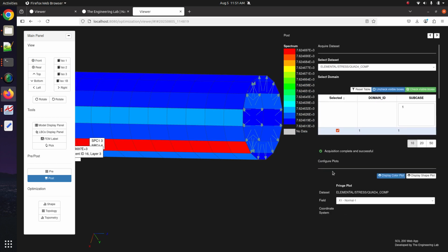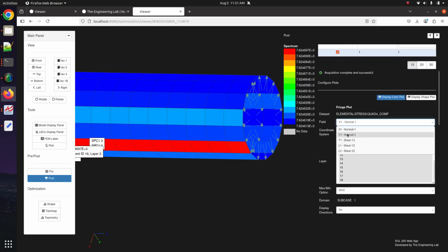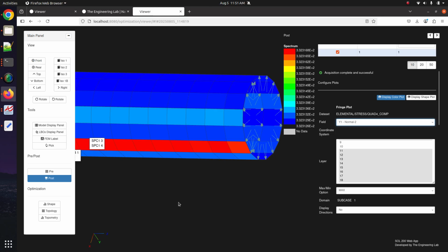Let's see, what else is there to do? You could look at the layer stress or ply stress in the 2 direction, shear stress, out-of-plane shear stress, I believe it is. So there are a few other things. So that's how you work with the PCOMP entry.